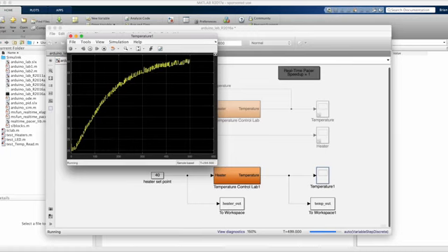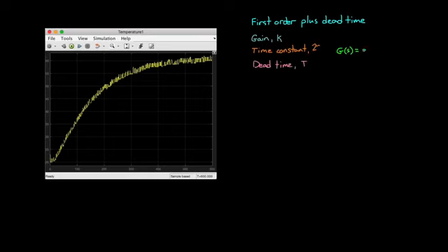And that's nearly the same step response that we saw earlier, except this time with a heater set point of 40%. I'm going to try to approximate this system with a first order transfer function. We'll need to include a delay term, or dead time, as well, since we already know that there's delay in the system. A first order plus dead time transfer function requires three things: the gain, the time constant, and the delay. The gain can be found by dividing the rise in temperature by the rise in the set point.